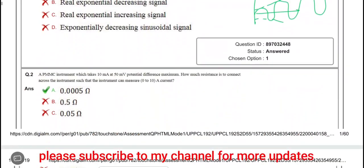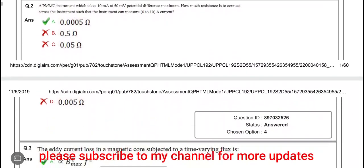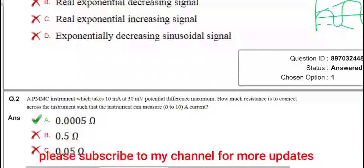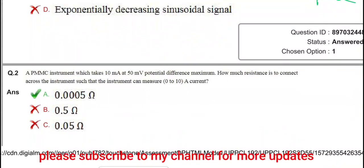Now here the question is about a PMMC instrument, which takes 10 milliamperes at 500 millivolts potential difference maximum. How much resistance is to be connected across the instrument such that the instrument can measure 0 to 10 amperes current? So here we need to increase the current, which means I will use shunt resistance.